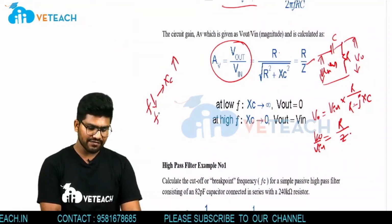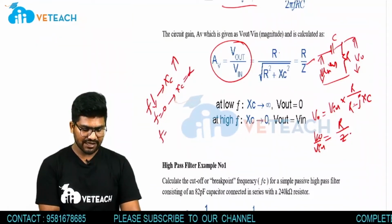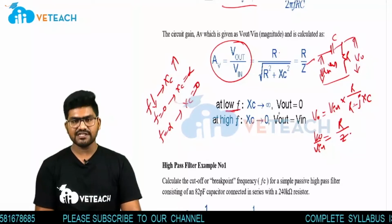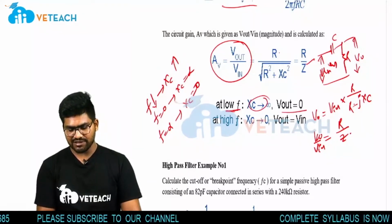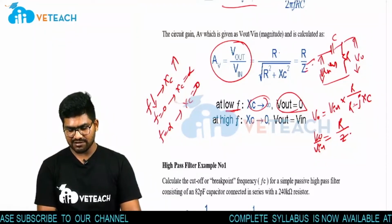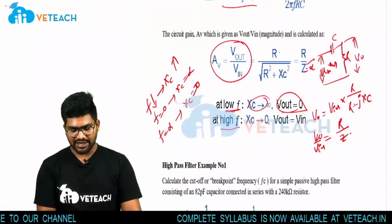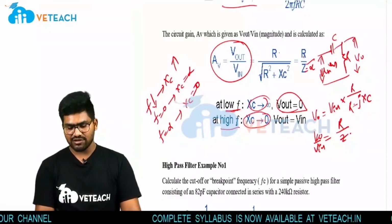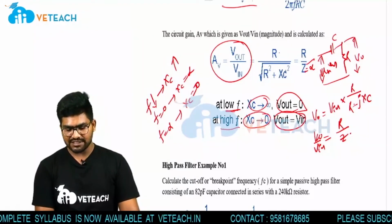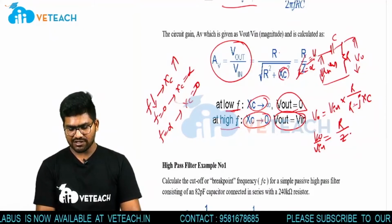If I take F as 0, Xc will become infinite. If F is infinite, Xc will become 0. At low frequency, Xc is infinite, that's why my V out is 0. If I substitute Xc as infinite, Z will become infinite, and anything divided by infinite is 0. Now at high frequency, Xc is 0, so V out becomes V in. Xc becomes 0, so it is simply R by R, which is 1. So V naught is equal to V in.